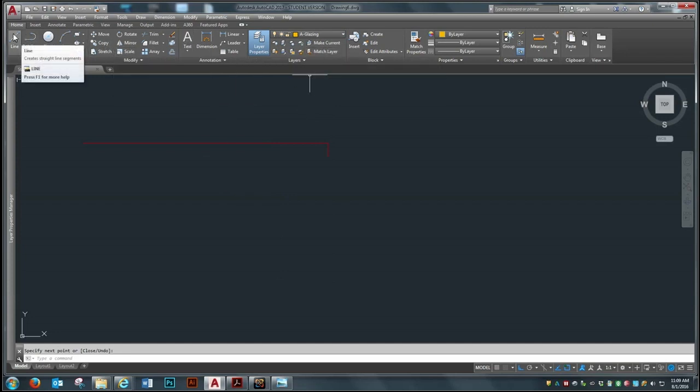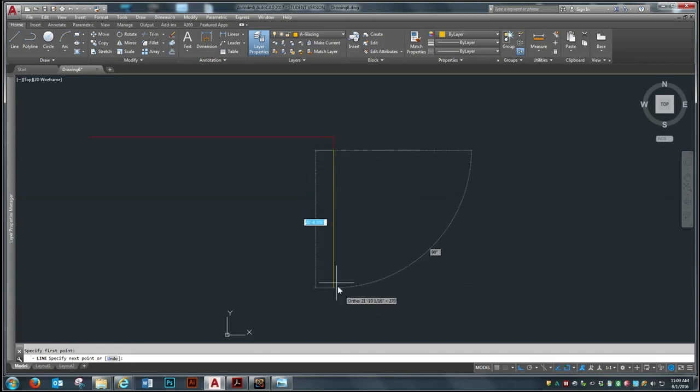We're going to take our line, attach it to the end of this 2-foot mark, drag our cursor down, and the window width is 10 foot 6-3/4, enter. And we'll hit enter again because the next line needs to be on a wall exterior.